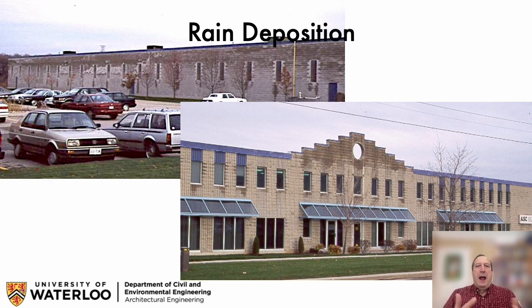So here's a couple of example buildings of the sort of long, not tall, but wide building. So you can see that all the rain is being deposited at the top in this building. And you'll also notice that there's some distinct drainage runoff coming from the windows, right? Not a lot of water is hitting the masonry walls next to it, and that small amount is being absorbed. In the windows, that small amount will not be absorbed, and so it runs down, and depending on the design of the windowsills, not great in this case, we see water dribbling onto the wall below.